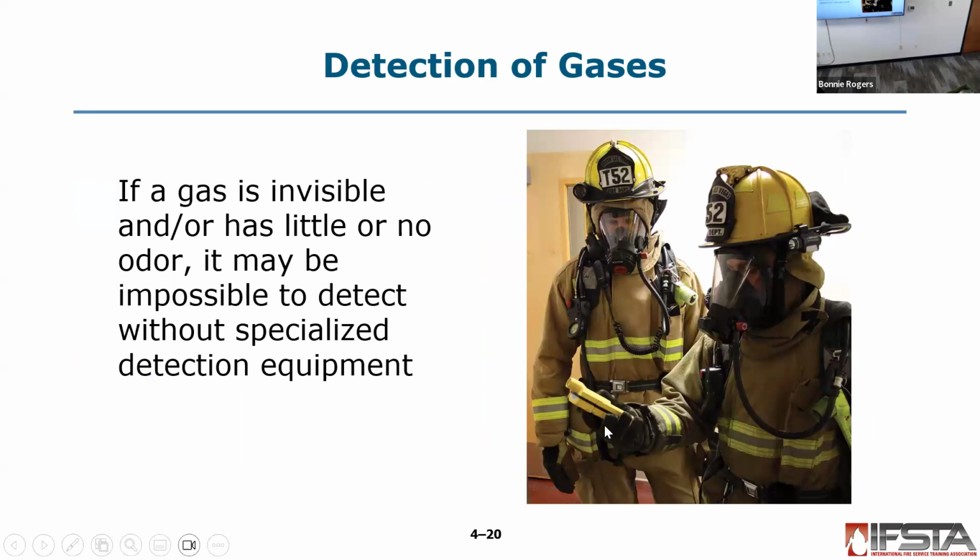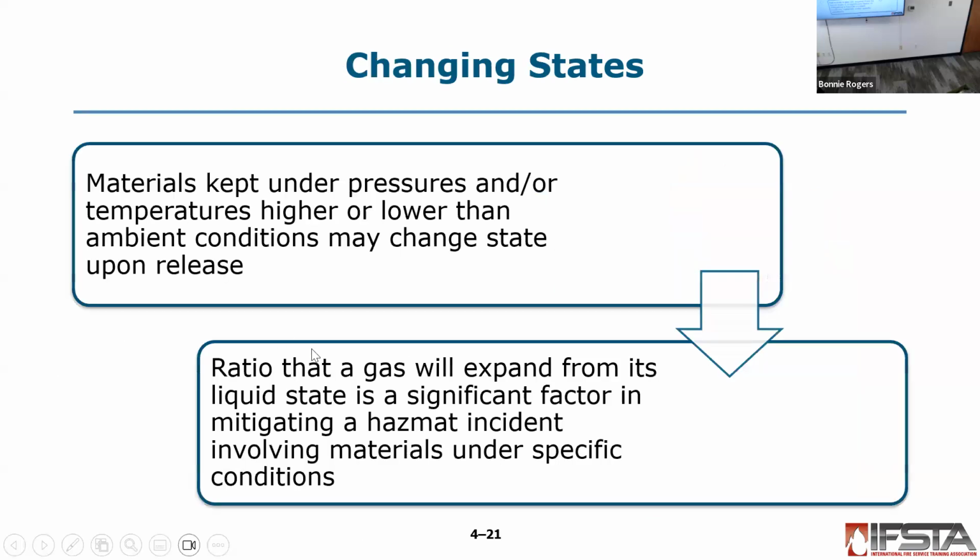We have four gas monitors that we can use. There's just a handful of gases that we can detect with them, whereas technicians have more specialized equipment that can detect more things. Don't rely on your sense of smell to determine if you have a hazardous material or hazardous gas. Because once you smell something, what does that mean? You've been exposed. Yep.